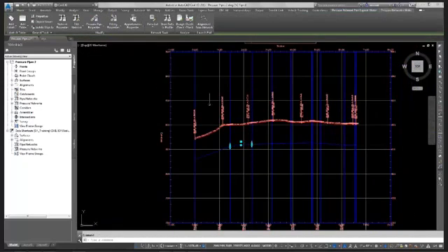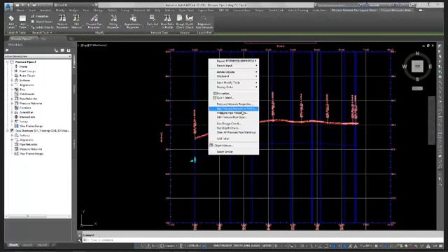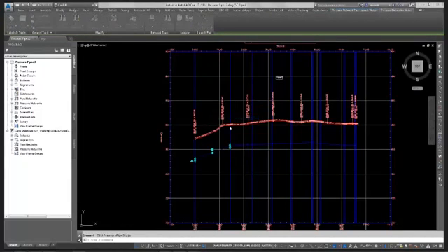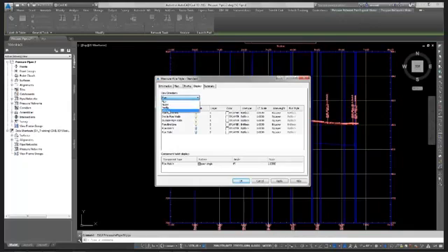That's weird that it's actually edit pressure pipe style. Oh, sorry, profile view. Forgot to switch. Switch it from center line, show inner pipe, outer pipes, and pipe ends, apply.